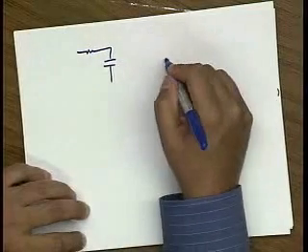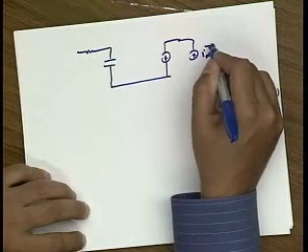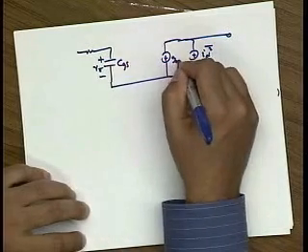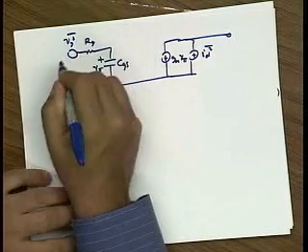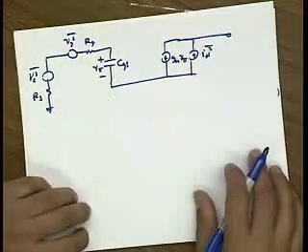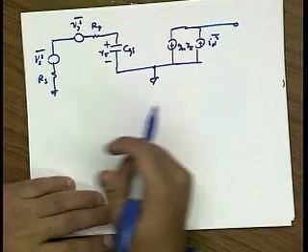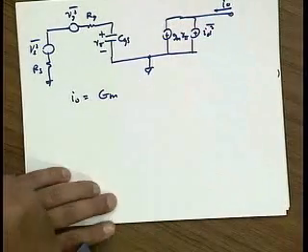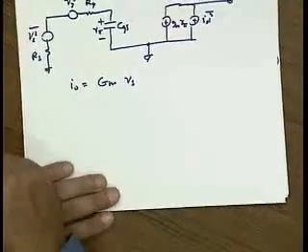So if I draw the simplified equivalent circuit, we're going to include the drain noise, CGS, let's call this V pi, gm V pi. This is our gate resistance, which generates a noise. And then finally we have our noise source and our source resistance. Okay? And I'd like to just recalculate the noise figure of this, making the observation that the output current, let's say I out, is some capital Gm times the source voltage. Okay? So I want to calculate that capital Gm.